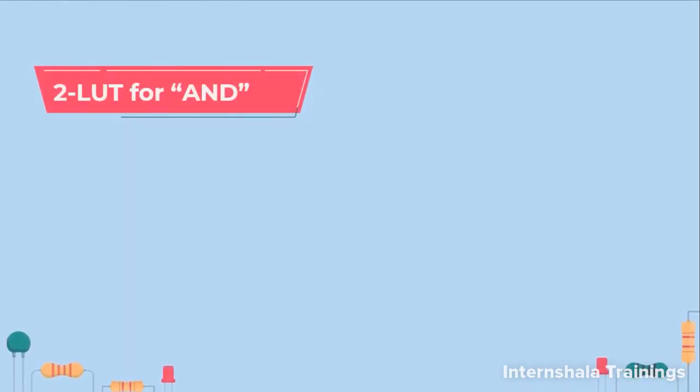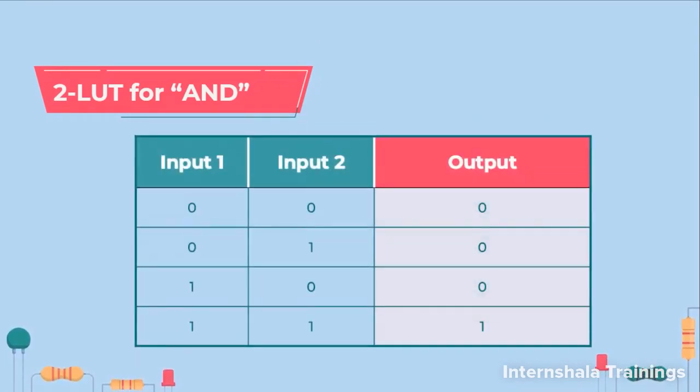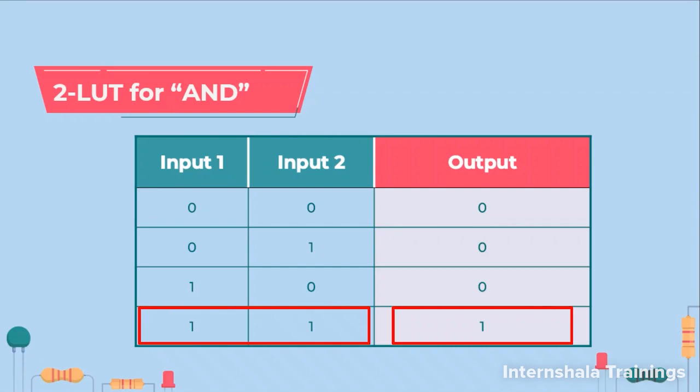So let us take an example of the easiest CLB that we can have, that we have shown in the previous example. That was the CLB computing the functionality of 2 input AND gate. So basically, out of all possible logic gates which were available inside the CLB, we used only one AND gate. We took 2 inputs and we decided that when both the inputs are 1, the output will be 1, otherwise the output will be 0, and the output is connected to the output port.